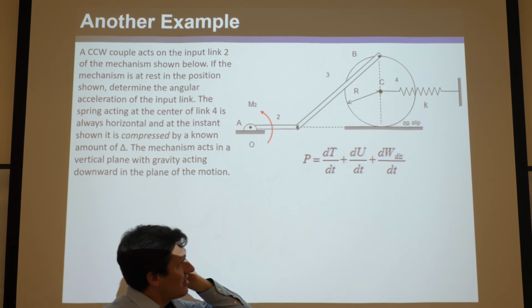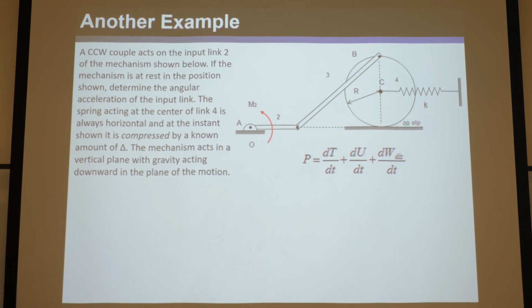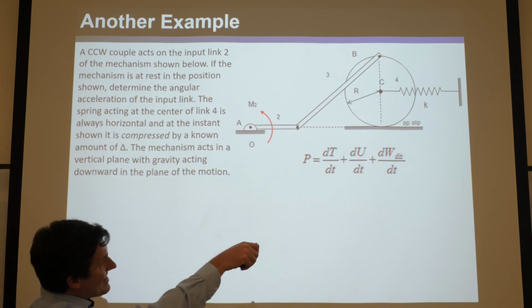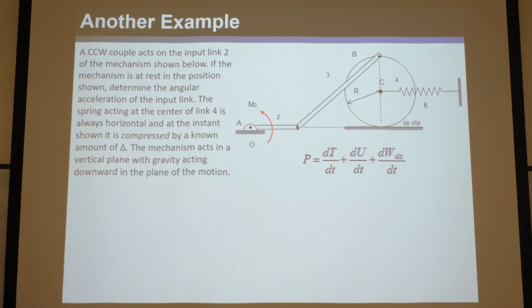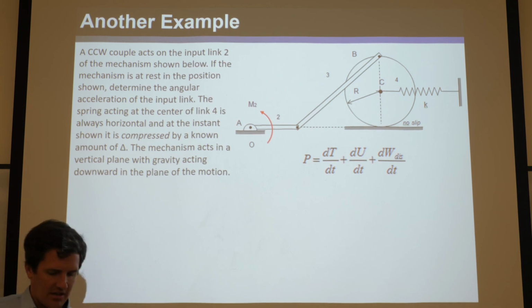But can we at least cancel the last term? Is there a dashpot in here? No, we don't see any dashpot. Is there any friction? Well, you always assume pin joints, maybe roller joints, something with very low friction, and you assume they're smooth. If this thing did rolling and sliding, the wheel there, the sliding would definitely generate friction, unless it said it was a smooth surface. But in this case, they say there's no slip. It's rolling, which you can assume is not generating friction.